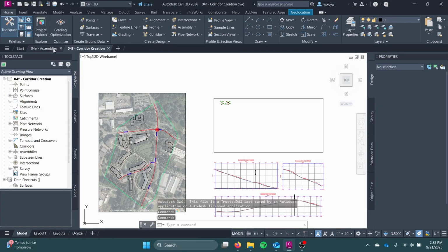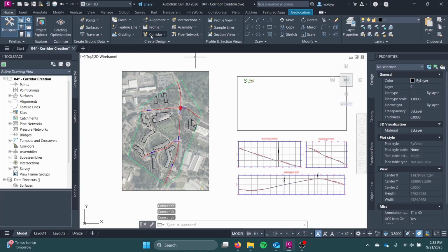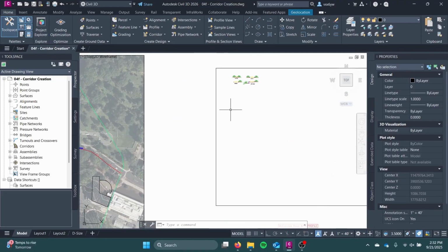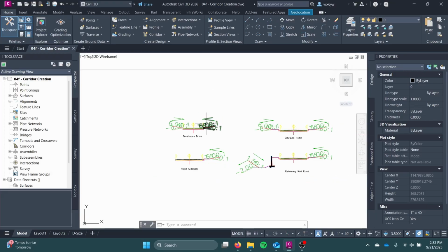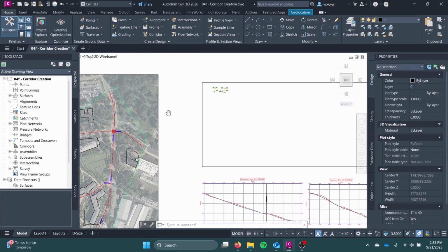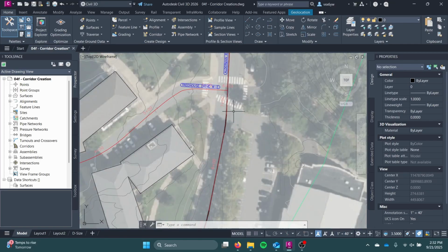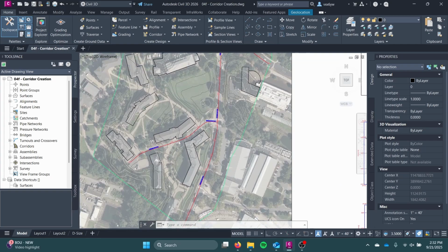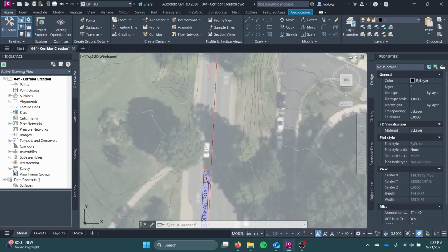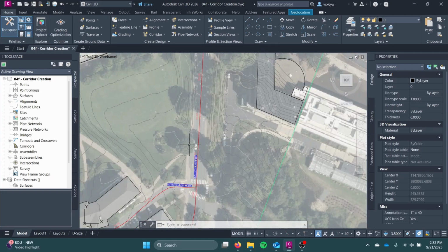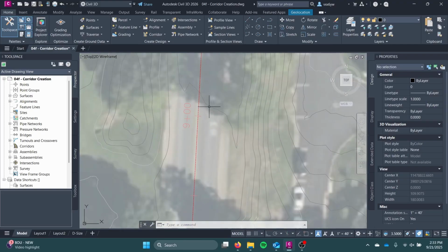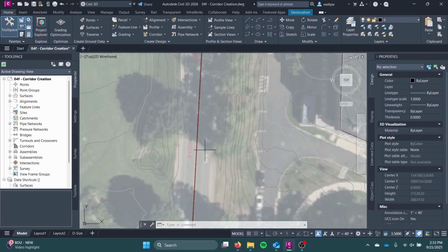Okay. Now that we're here, the way the corridor tool works, also in the Home tab under the design tools, is it takes these sections that we made, and you can take this section and assign it to an alignment. When you assign it to an alignment, you choose an interval that the section is repeated on. For example, I could say every 20 feet on the alignment, it creates a section.